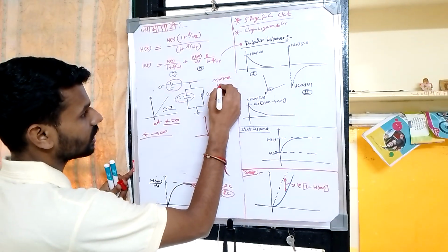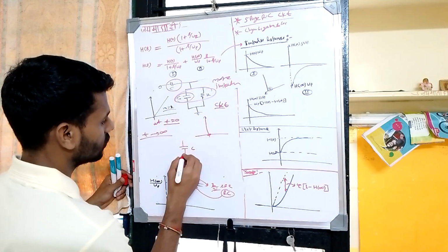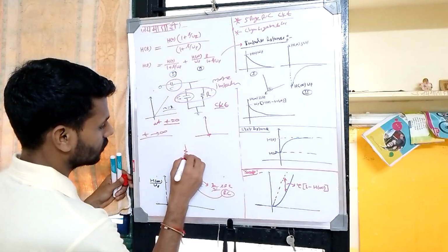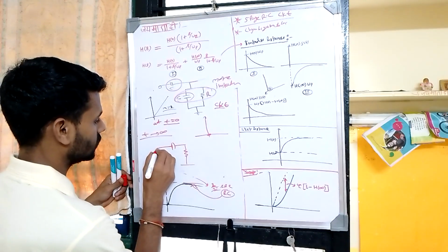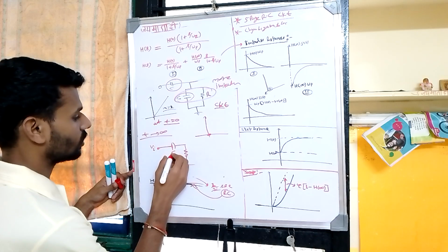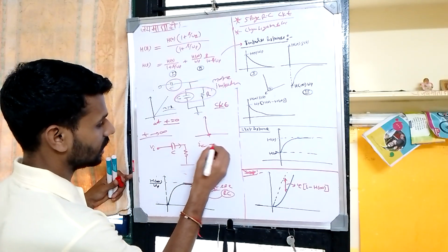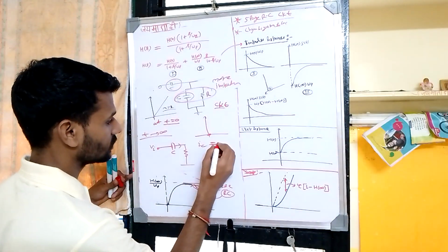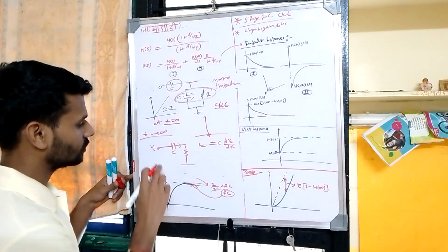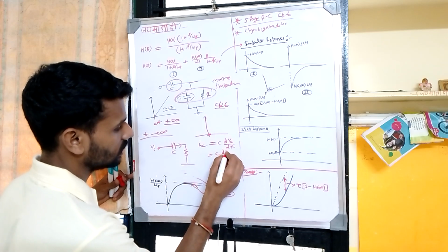Impedance is very high, so this circuit will look like only C, meaning it is open circuit. In the parallel combination, the less impedance is considered, so it will look like only R, and this will be my capacitance C. Because the capacitance has very high impedance, the total input drop at t equals infinity will be across it. So the current through the capacitance, IC, is C dVc upon dt, and since the capacitance impedance is very high, the total input drops approximately across the capacitance, so this becomes C dVi upon dt.